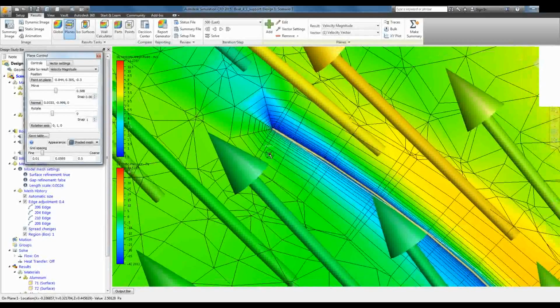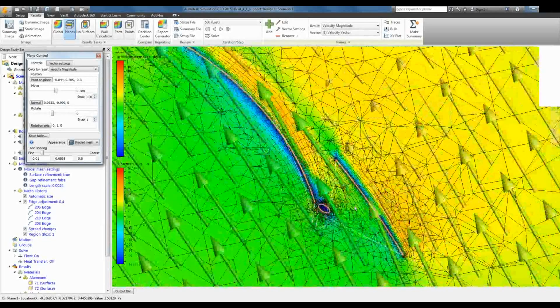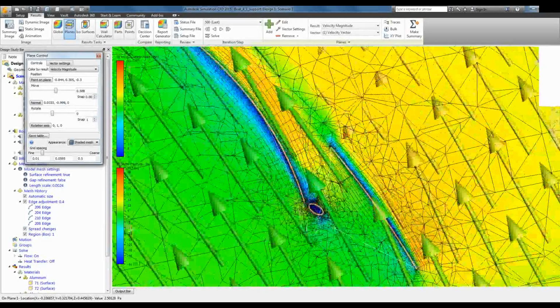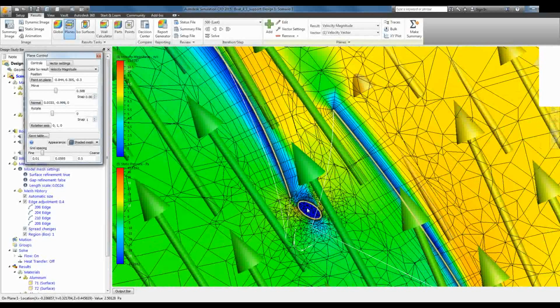So one other area that might be of interest is the interaction between the jib and the main. Here's the mast. Is there something we could have done with the mast to actually eliminate some of this pocketing that's going on behind it? Now, there have been some studies where they are trying to turn the mast depending on which angle the boat is to the wind. An awful lot of mast studies are being done, especially on smaller boats, where they're trying to bend the mast to pre-bend it to affect the shape of the sails.